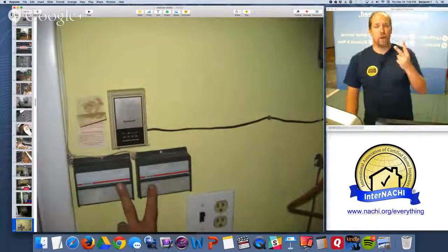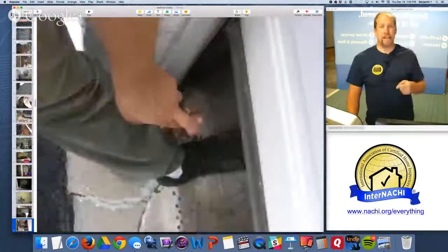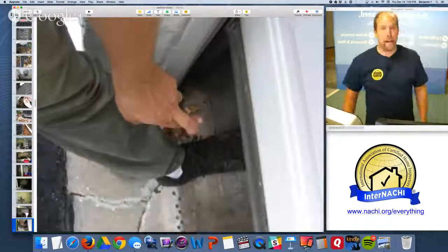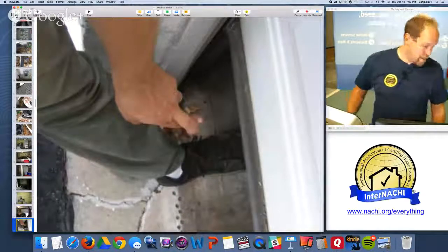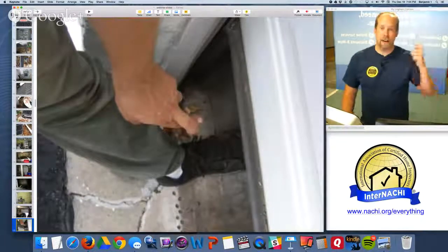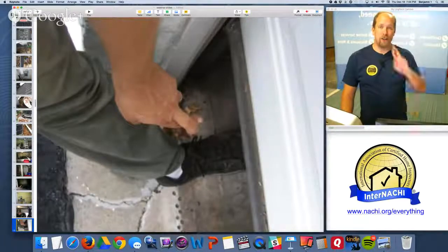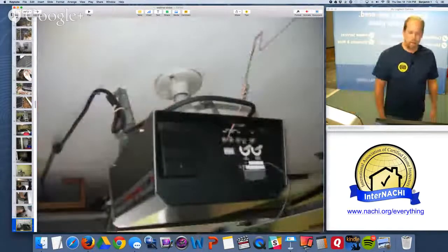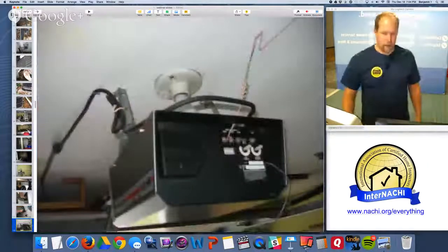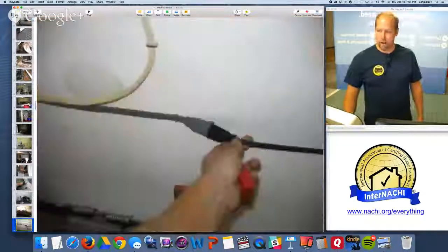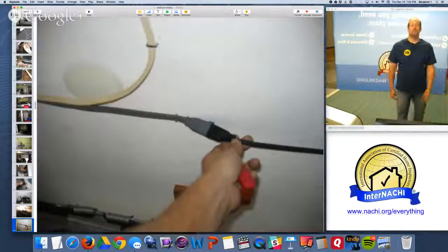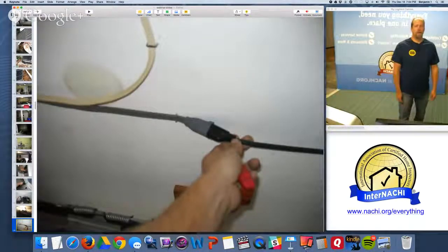I've got 2 garage door openers. First thing I like to do is open them up and close them and test the safety eyes, the reverse laser beams. And they're not there. They're not installed. So again, an X tells me not installed. So there's one of the units installed there, and it's plugged into an extension cord. Extension cords are for temporary use only.